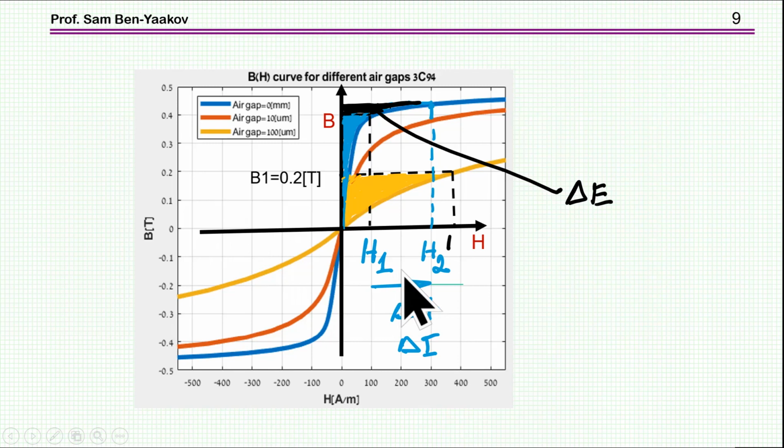Now, energy storage is not the purpose per se, but if you have a converter, say, and you need an inductor that will carry a certain current, this means that the inductor has to store energy, because you have an inductance and then you have current. So even though in many applications you are not really looking for energy storage, what determines the ability of the inductor to function is its ability to store energy, because when you pass current through it, you actually store the energy.